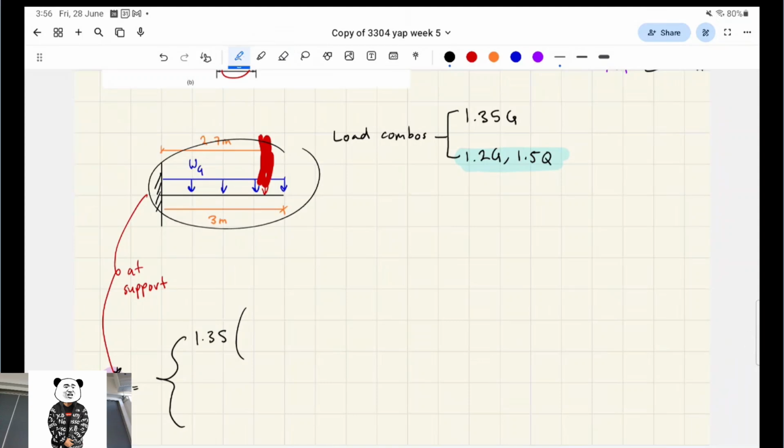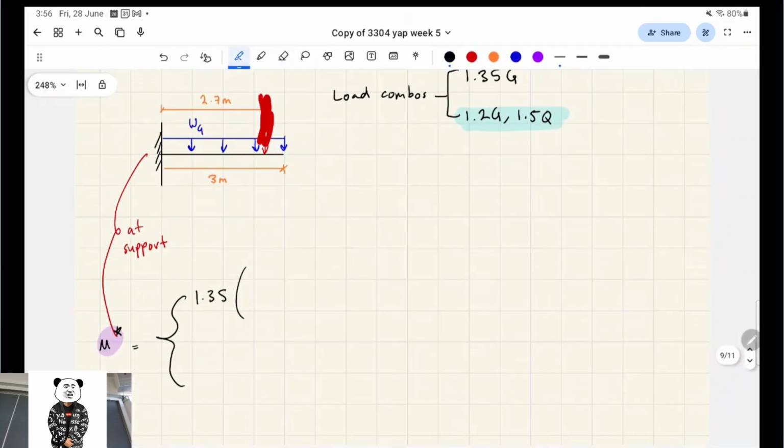How do you calculate bending moment, firstly? Point load times distance. Yes, but we don't have a point load. We have a distributed load. Convert it. Convert it, very good. So we have to find what the equivalent load is. Remember that this value here was 13.832. We multiplied by 3, so now we've got the force.